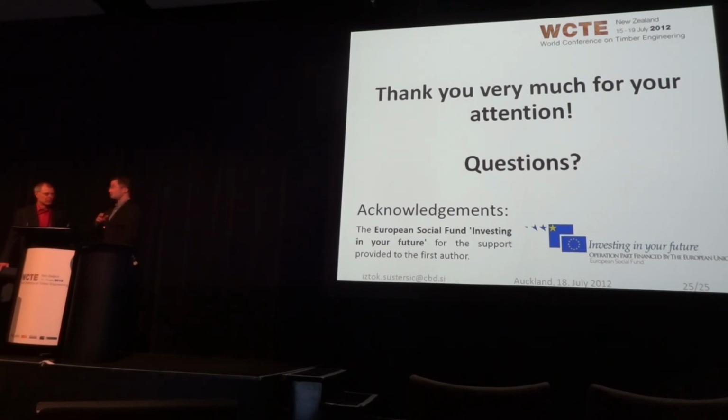So we often just use the BMF 105s, but of course that's for maybe 1 to 2, maximum 3-story buildings. Of course, when you come to more stories, we have to use hold downs. You see, in Canada, we would always use the hold downs even in 1 or 2-story buildings, and that's the standard practice. And what about the rocking shear walls?